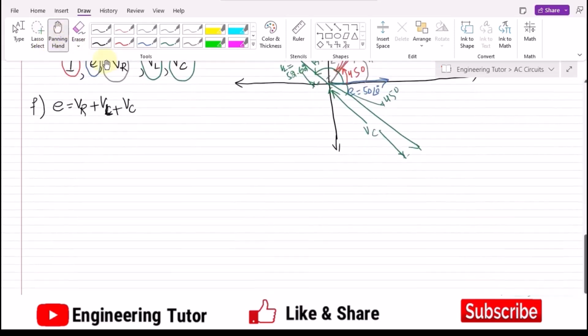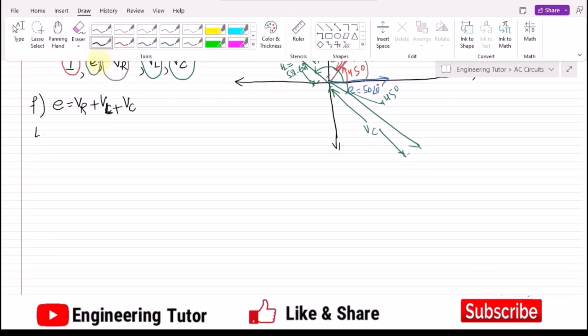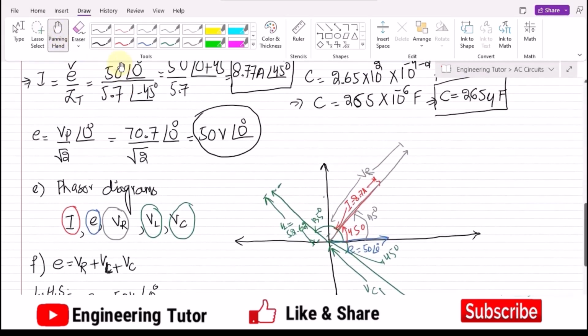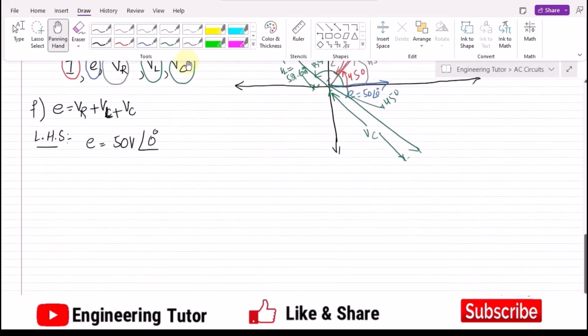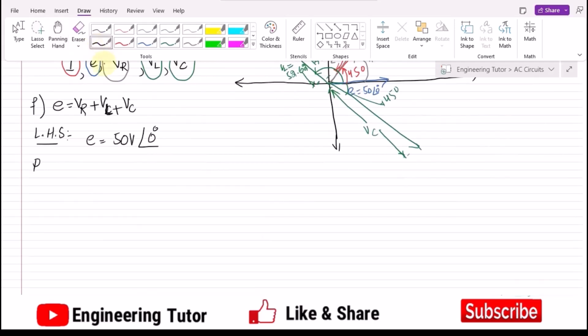Okay, so in order to do it, let me start from the left hand side first. On the left hand side we have the voltage, and that is 50 volts and 0 degrees, and we can also confirm it from here, that the total voltage in the polar form is this one. Now going toward the right hand side, we have to see whether the summation of VR, VL and VC is equal to the total voltage or not. So now writing their values here, the value of V of R is how much?